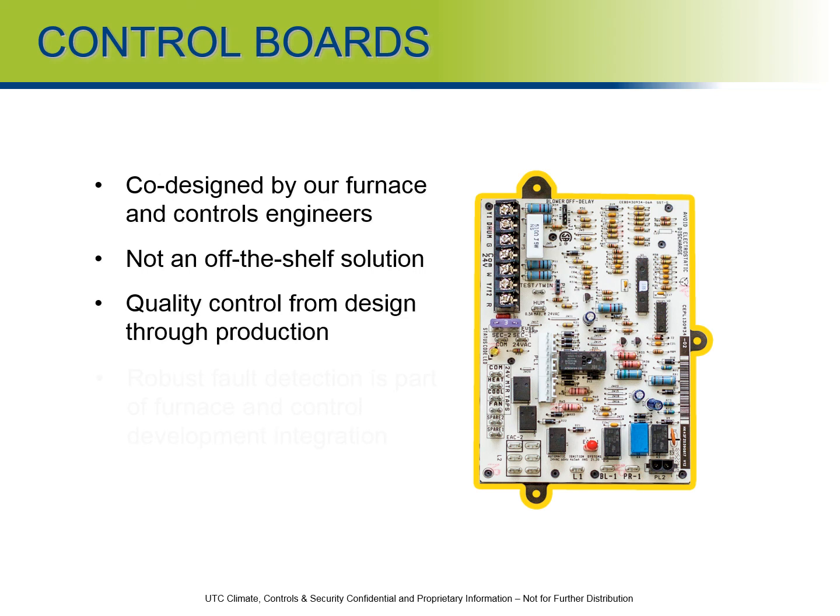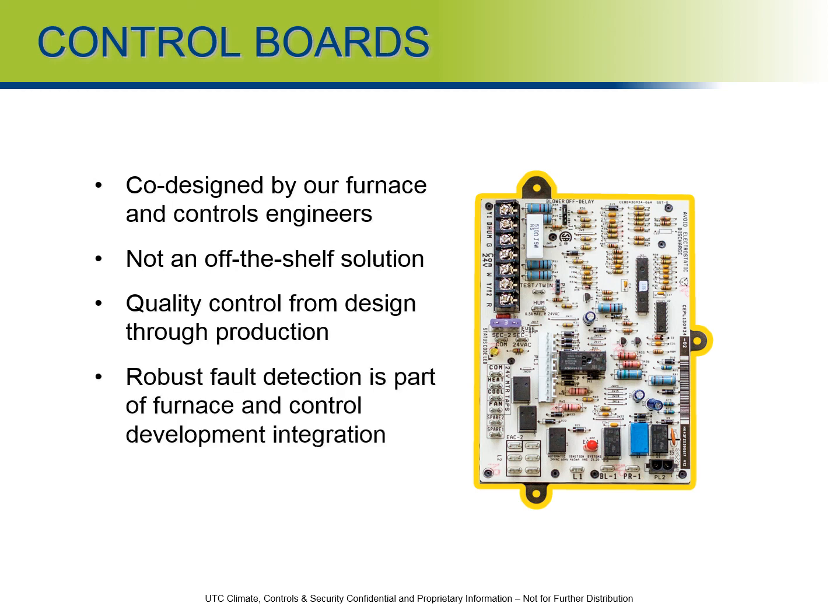A lot of these control boards now in the furnaces are designed by the manufacturing engineers, and built from the ground up by the manufacturer. That all includes the fault detection, also the programming for the ECM motors, blower speeds, and airflow ranges, all of that is done by the manufacturer nowadays.